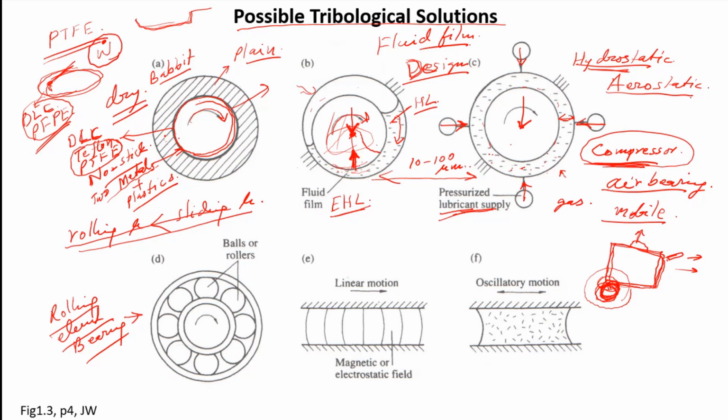What did you say? Could you say it again? Generally we see that without any elastic deformation, it cracks and wears out. Yeah, after repeated use, yes. But when you have a new pan and it has the coating, it doesn't get removed so easily. PTFE by nature is very ductile, so it will undergo plastic deformation, but after repeated use, because of the thermal action, its molecules have changed. So it has degraded, and that is a form of thermal degradation.